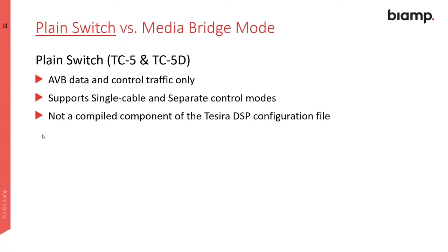So you will not have a block. Anytime you have a Biamp device, usually you will have a block dedicated to that Biamp device. For example, if you have a Tesira Forte, you will drag a Tesira Forte and place it into your software. If you have a Server I/O, you will add all the inputs and the outputs of that particular Server I/O. In the case of the TesiraCONNECT, you will not have a block. It is a connectivity box to your devices. You will be able to discover it through the software, through the device maintenance, but there is no dedicated block in the device.